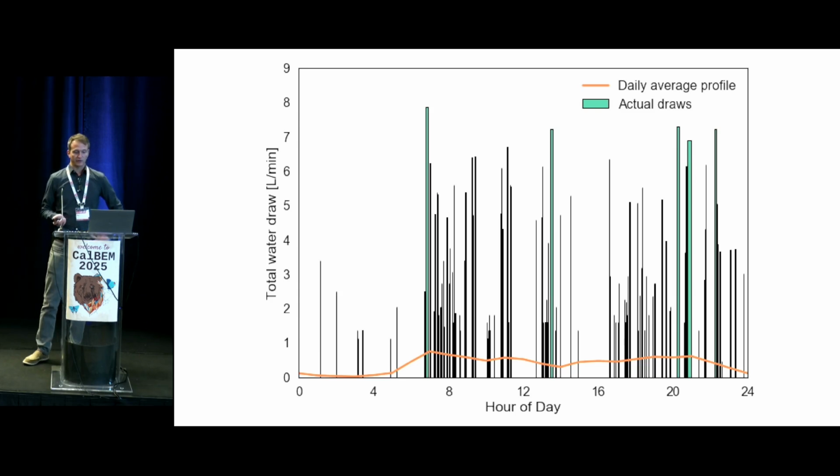For example, a 10-minute shower at 2 gallons per minute would be a very different scenario for the heat pump water heater than a 1-hour shower at 1/3 of a gallon per minute. The big difference is you're never going to trigger that backup resistance heat if you are simulating these at an hour-long time step.